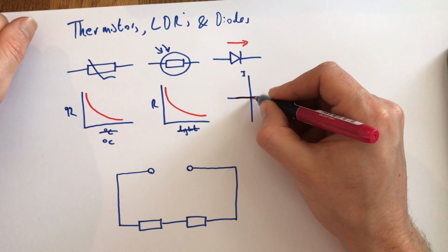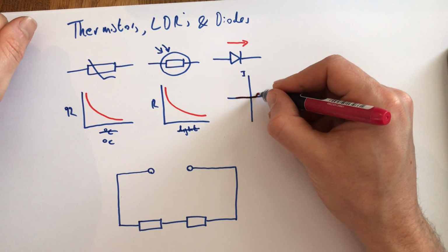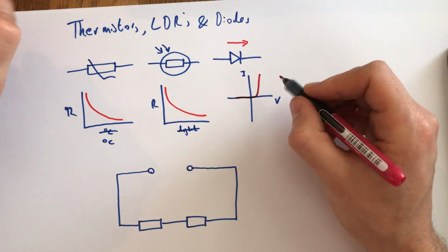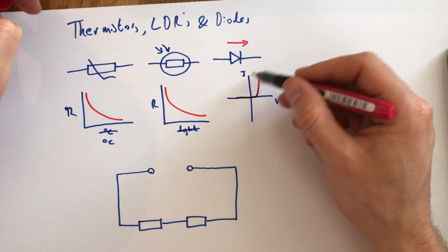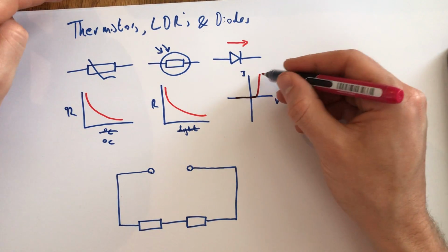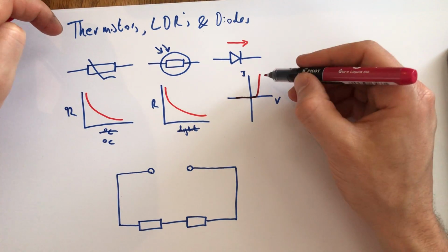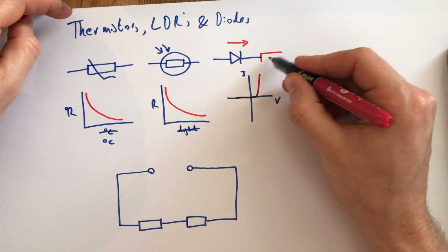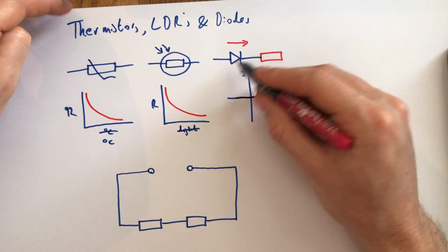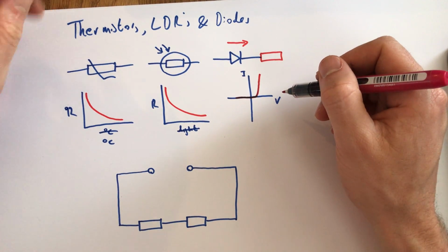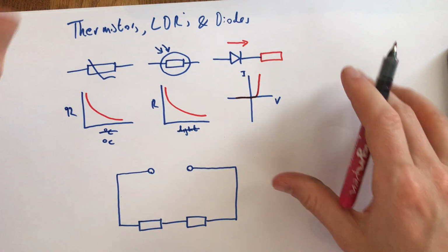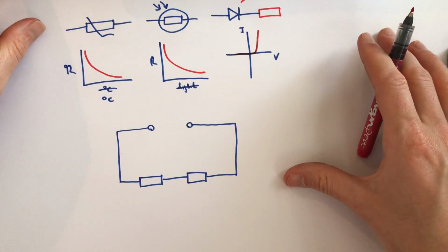Then, at a fairly small level of voltage, the resistance suddenly decreases dramatically. Now this is only for a very small range. There's a limit to this, so that if you put a high enough voltage across it, you're just going to break the diode. So diodes are usually connected in series with a resistor, so the current doesn't get too high in them and break them. Unfortunately, it's not particularly interesting when they do break; it just stops working.